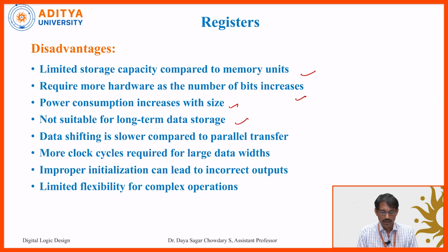Not suitable for long term data storage. So, we cannot store data for the long term, and data shifting is slower compared to parallel transfer. So, this is also one of the disadvantages for these particular registers. More clock cycles are required for large data widths. As we know already, this is a synchronous circuit, that is fine, but if there are asynchronous circuits also, then definitely it requires more clock pulses. And improper initialization can lead to incorrect outputs, and they are limited in flexibility for complex operations.